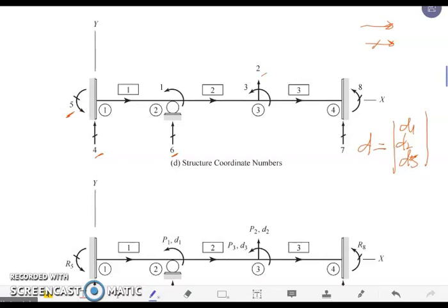At joint 4, we have restraint coordinates, 2 of them: translation along the y direction, and of course rotation. We number first the translation along the y direction, so we have 7, and the restraint coordinate for rotation is numbered as 8. So if we now identify the number of restraint coordinates, we have here our R.